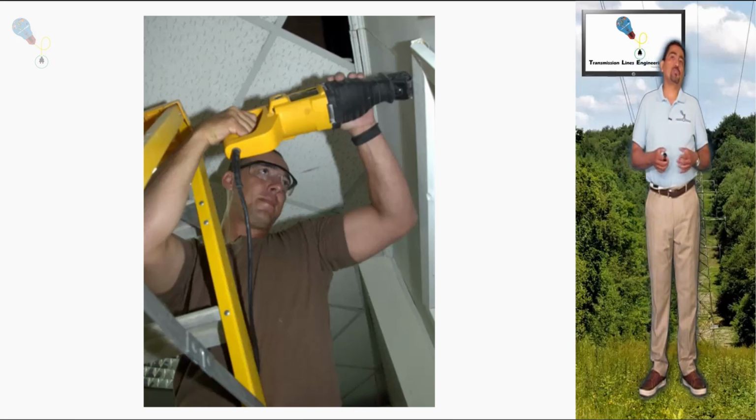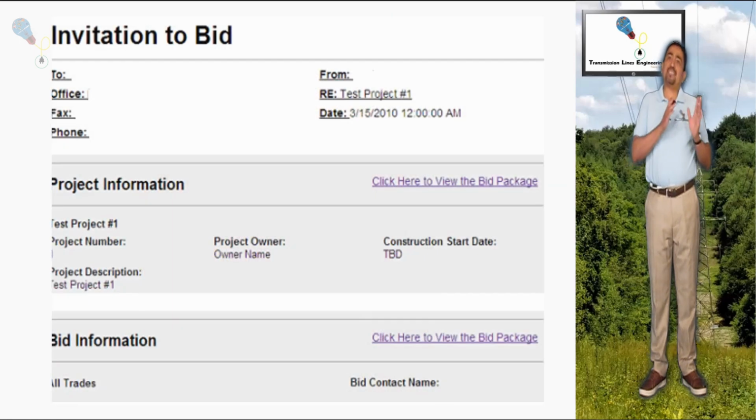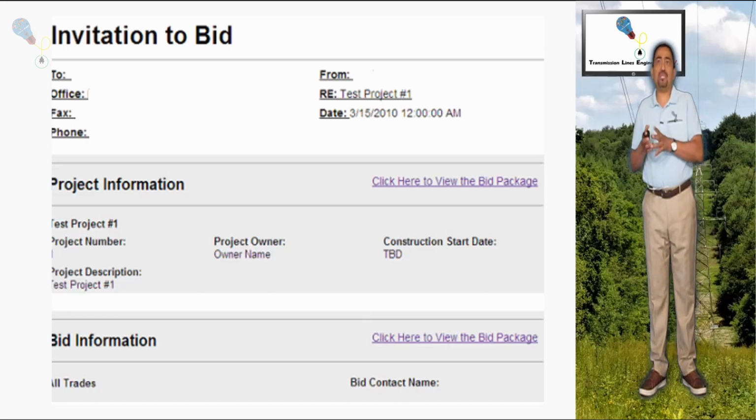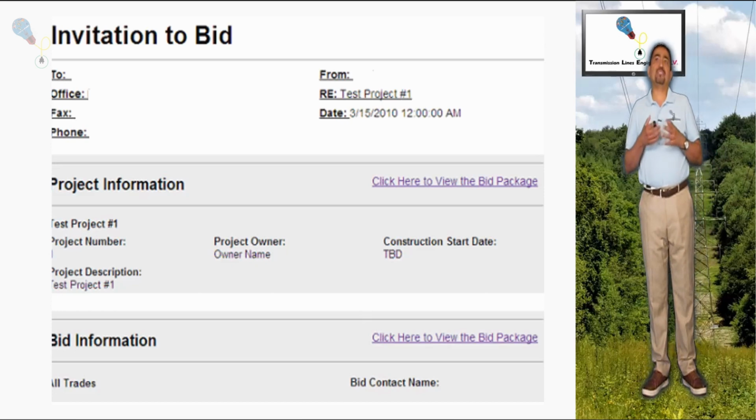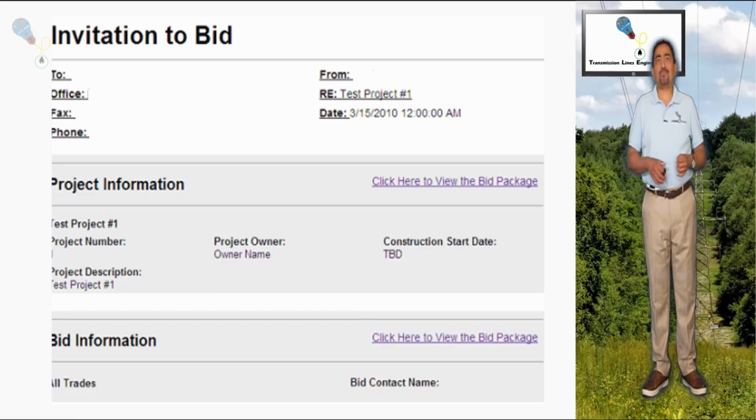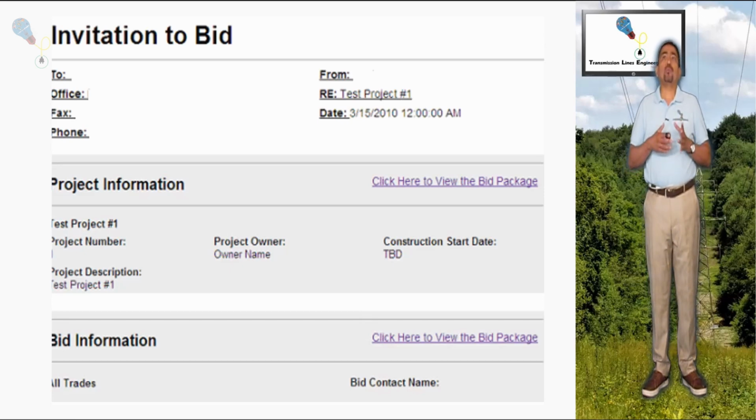As step number two, once the client determines the possible alignments, the first document will be written, which will serve as a basis for the engineering and construction consultants for detailed design and construction. It will create what is known as a design basis memorandum, a DBM.